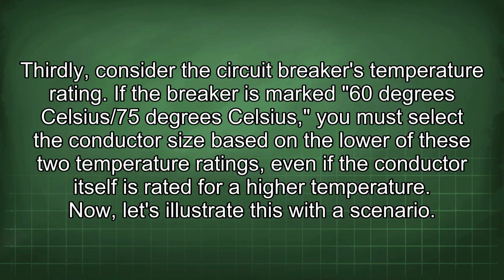Thirdly, consider the circuit breaker's temperature rating. If the breaker is marked 60 degrees Celsius/75 degrees Celsius, you must select the conductor size based on the lower of these two temperature ratings, even if the conductor itself is rated for a high temperature.